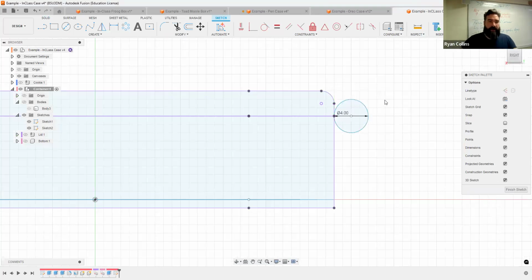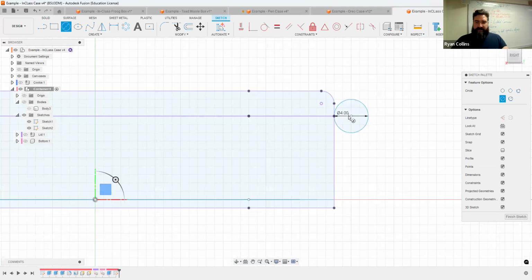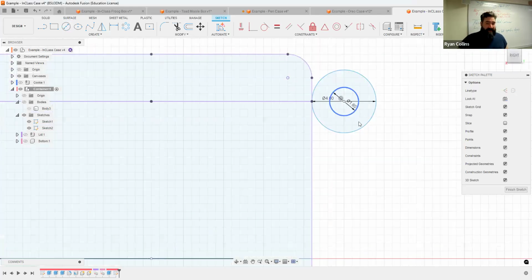There we are. Okay. And I need a hollow space. The filament is 1.75 millimeters. So let's make that 1.8. Yeah, you usually want like 0.1 to 0.3 clearance between things that are going to be printed, because it squishes a little bit. Okay, that's basically it.